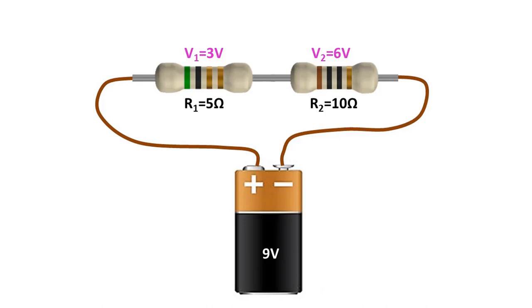Even if more resistors were connected in series, we would have to calculate in the same way. We can calculate the voltages on the resistor in this way without finding the current value. In addition, the total voltage consumed by the 2 resistors gives the source voltage. Otherwise, we would have miscalculated. This is the working principle of series-connected circuits.